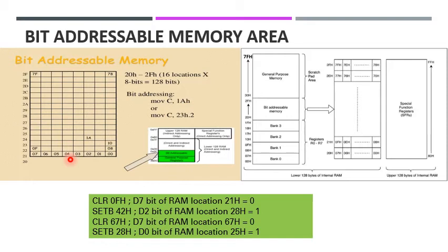The program status word has an F0 flag, which is a user set flag. This flag can be copied to bit addressable memory for monitoring its status. You can check out a list of all the bitwise instructions in 8051 over here.